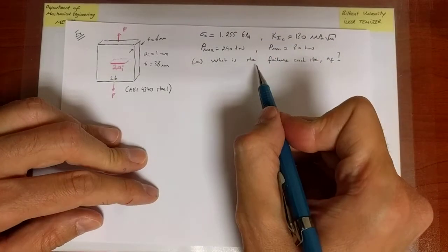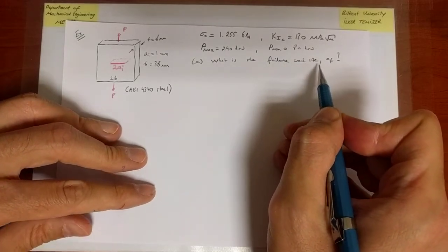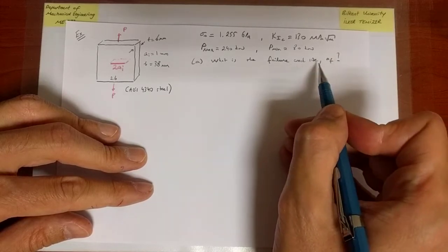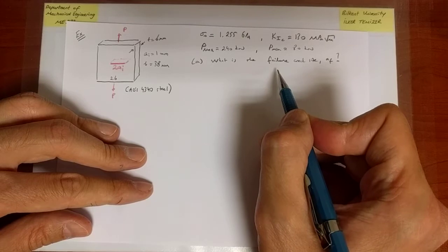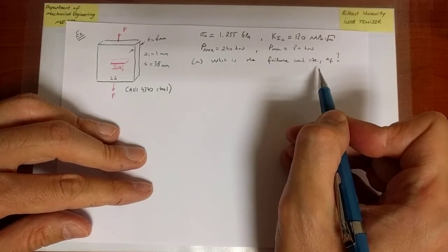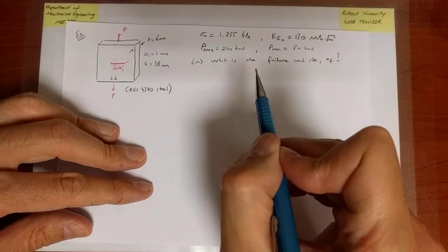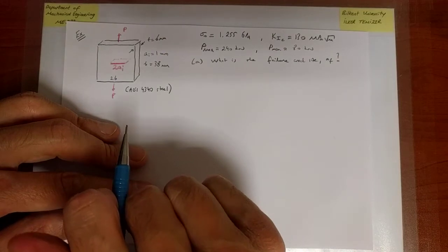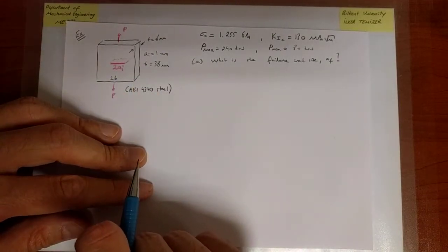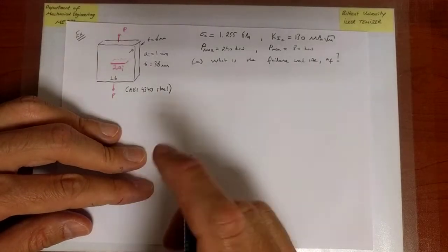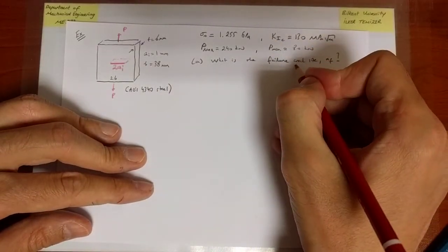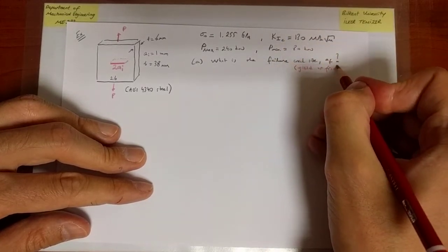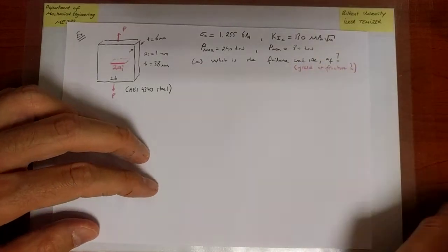Now, the question does not need to explain further than that, but you will see we will decide the size of the crack depending on whether fracture or yielding happens first. Okay, and remember the idea of the transition crack size. So that's something we could be using, or the analysis that I will do is something we could be using. But we have an idea that one or the other can be more critical first. So yield or fracture is really the underlying question here.